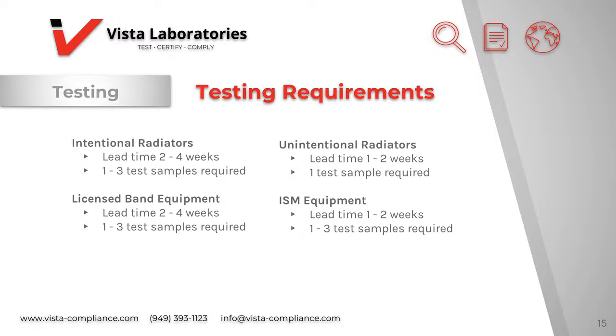Sample requirements may also depend on the antenna type and if it's removable. Generally, separate samples are needed for the RF conducted part and the radiated measurements. Samples must also be able to sweep over the full spectrum continuously. If there are multiple radio functions, multiple samples will be required if each sample only supports a single radio function. The measurement process will naturally take longer if there is a need for troubleshooting.